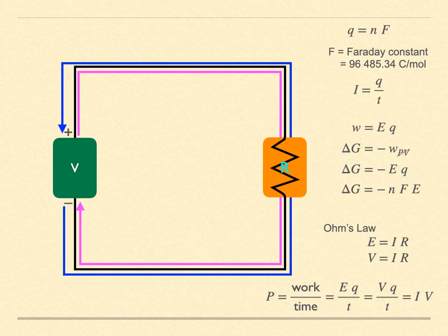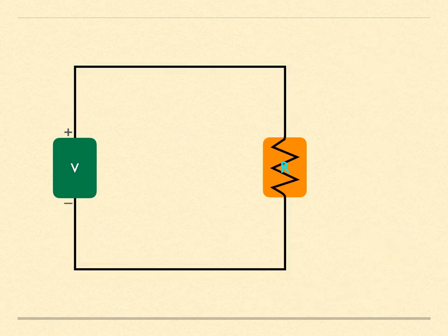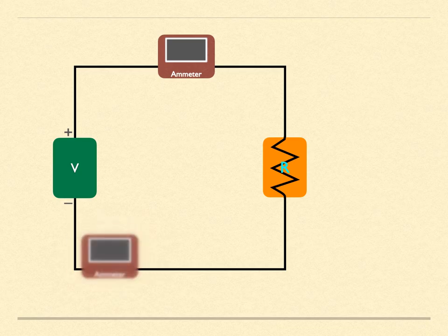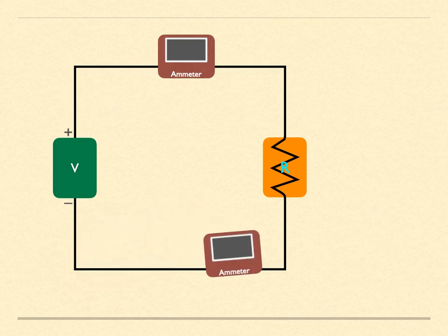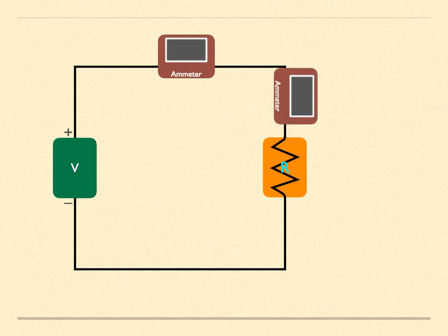There are two important tools that we use in analyzing electric circuits, an ammeter and a voltmeter. They are used to measure respectively the circuit current and the voltage drop across a section of that circuit. An ammeter is a low impedance device. It has very small internal resistance. It is designed to minimize its effect on the circuit it is analyzing. You place it into the circuit. It doesn't matter where you position it, for the current is constant throughout the circuit. If you have a circuit with parallel paths, the current is constant in each leg of the circuit, and they likely are different. The ammeter can be used to measure each leg separately if properly positioned.